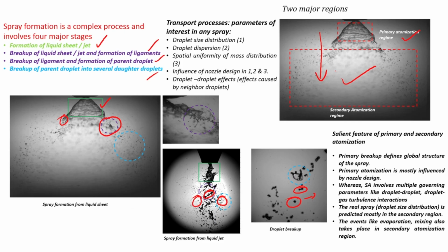In between, the droplets start to interact with the flow, which has an effect on droplet dispersion, how the droplets are spread, and how much they evaporate. All those things start to happen when a spray is injected into a high velocity gas phase flow field. Events like evaporation and mixing happen a little later. It does not really happen there because this process is very fast.